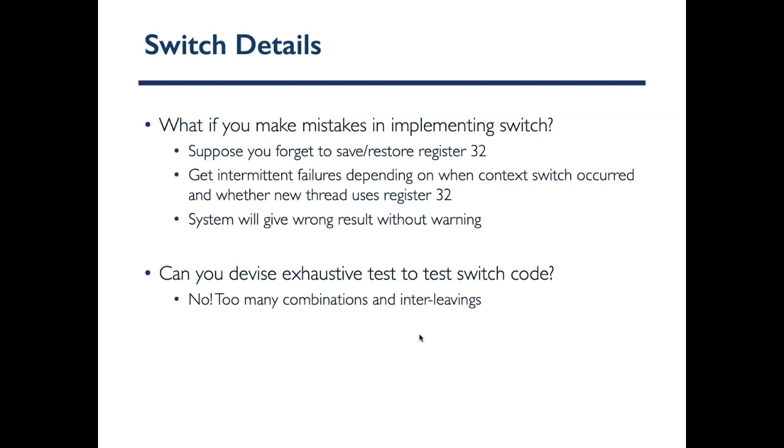But if you actually make a mistake and don't save the registers that you have to save, you may or may not face a problem. Let's say there was one register that you forgot, but most of the time no thread uses this register, or maybe the compiler never uses it. So you're going to be fine. But then you start running code that uses that register and you haven't saved it, then you start seeing a lot of errors in your code. So it's really important that this is implemented diligently.